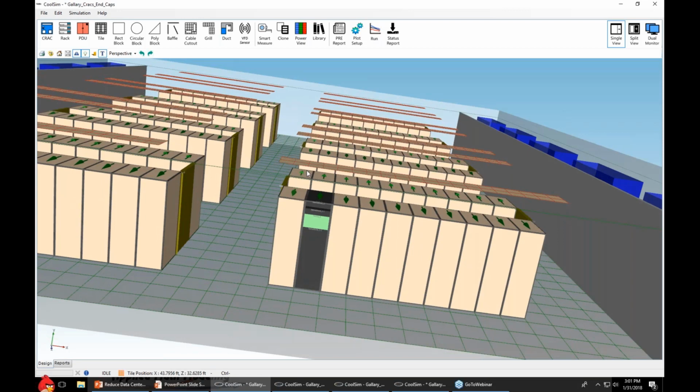All right, when increasing the supply air temp, if the server speeds up, the additional kW increases inside CoolSim? Yes, exactly. Question from Mark. So what happens is we're using the fan laws inside of CoolSim to do the prediction of cost. So if the supply air temperature goes up, then probably the fans will blow harder. We saw that in our last case.